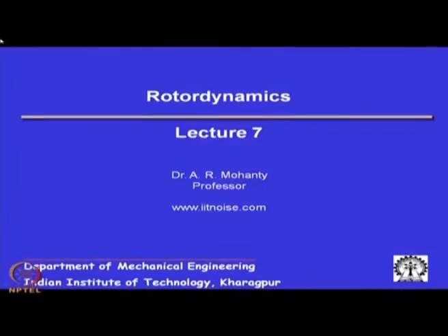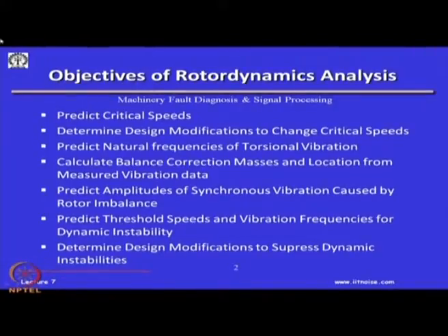Okay. And in practice, we will find many rotor systems comprising turbines, compressors, pumps with sets of impellers, or fans with sets of blowers, and so on. So, it is very important that we understand the physics of such rotating machines, and how we try to control the unbalanced forces, control the rotordynamic stability, calculate the critical speeds, and so on. The basic objective of rotordynamics is to predict critical speeds. But let me explain what I mean by a rotor system.